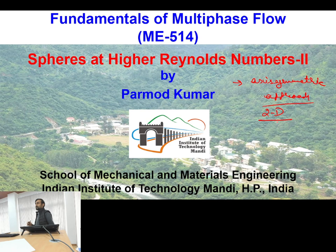And in this two-dimensional approximation, what we will be having? In this two-dimensional approximation, I can use the Stream-Vorticity method. Okay, because stream function and vorticity function are actually applicable for two-dimensional flow field. So whenever we are having a two-dimensional flow field, then the use of stream function and vorticity field gives us nothing but a lesser number of variables. Okay, so these will be making our analysis simpler.